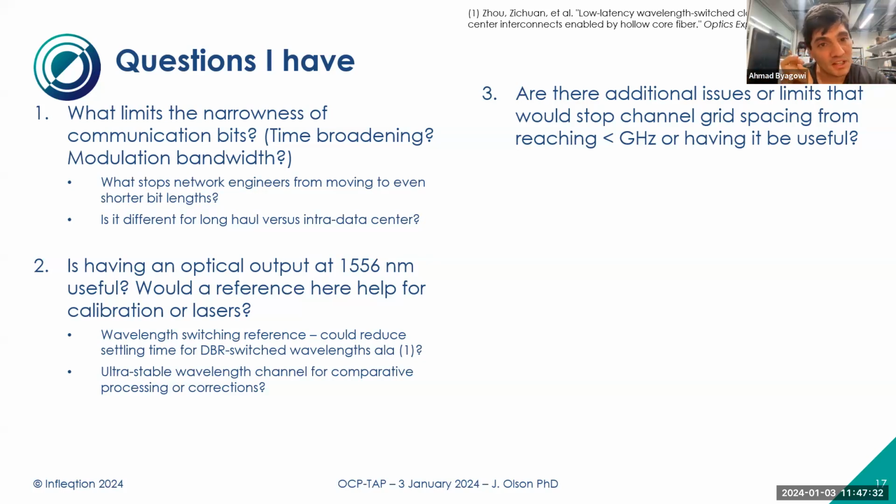Again, this is in the frequency domain. In the time domain, again, we rely heavily on that eye to be open. Imagine if, I'm not saying we can do something if the eye is closed, but we could have the capability to detect things at lower SNR if you know precisely when you have to run your assessment and your threshold, say within a picosecond. To get to that point, you need the synchronization between the two parties to be precise enough.